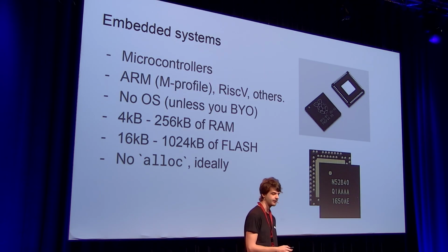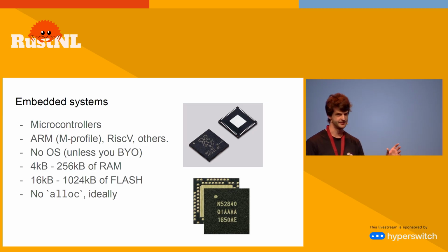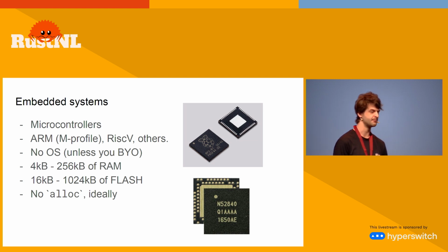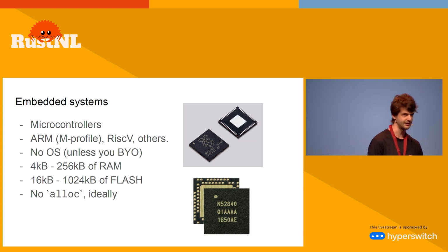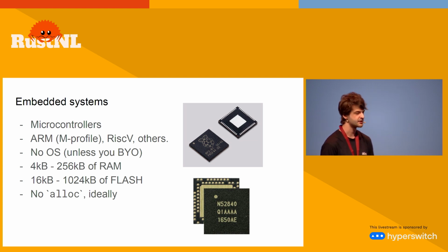When I say async for embedded systems, embedded is a very wide term. I'm focusing mainly on microcontroller-based embedded systems, not embedded Linux, like routers or kiosks, but just microcontrollers. These are really small chips, commonly using architectures like ARM M profile, which is more restricted than the ARMs on your phone, or RISC-V, other architectures. They come with no OS. From the moment you apply power to the chip, the first instruction that runs is your code already, unless of course you can bring your own.